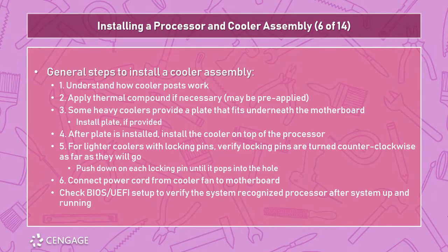Go ahead and check UEFI to make sure that your system recognizes the processor, and maybe run it for about a minute or two, just without load, to see that the temperature is nominal within range. That's where you're going to want to check your documentation for your CPU to make sure that it's operating at the correct range.